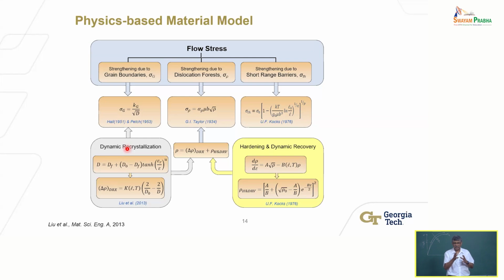So recovery, recrystallization, grain growth, you may have come across in a basic metallurgy class. There is an analog of that which can happen purely due to deformation. That's what dynamic recrystallization is. In other words, I can cause new grains to form through deformation, essentially by breaking apart the existing grains through these dislocations and forming new grains.